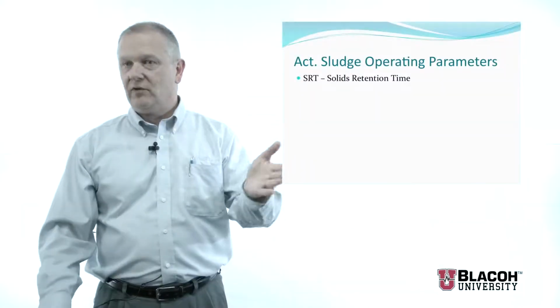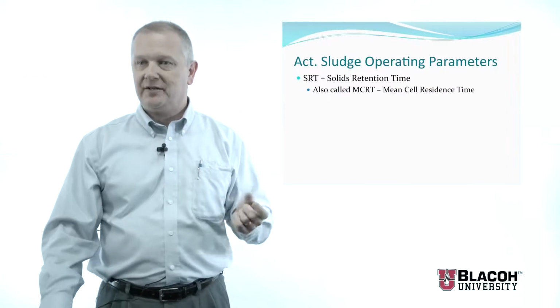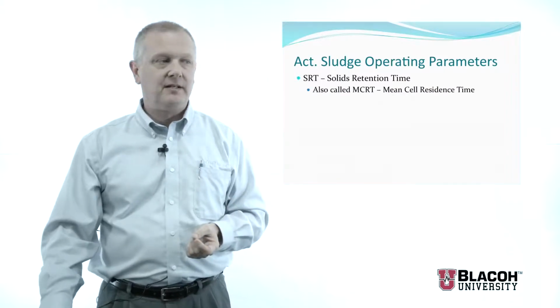Even more important in this type of system, though, is the solids retention time. How long do these microorganisms stay in the system? Since we're recycling them back from the clarifier over and over again, the solids retention time is much longer than the liquid or hydraulic retention time. We also call this the mean cell residence time because these are bacterial cells that we're talking about.